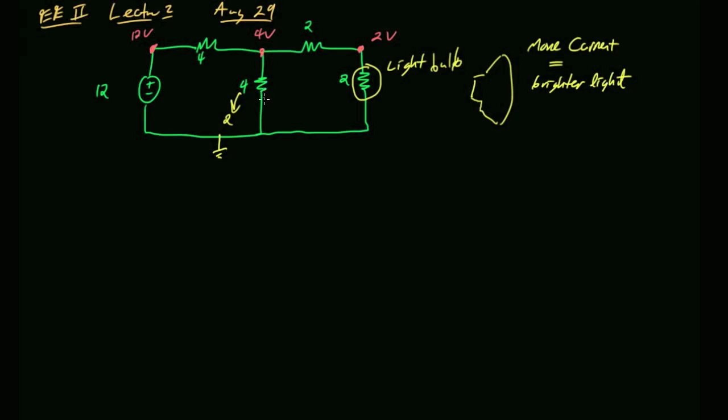Stay the same is an option. Can we argue that the light will get dimmer? Why would it get dimmer? There might be a case for that. There's less resistance, so more current passes through there. Current will flow through the less resistance. If this resistance gets lower, then electrons that make it to this intersection are more likely to want to go this way, because they prefer the path of least resistance. So it could be the case that by lowering this resistor, you divert more current into this path, which means less current in that path, which means the light gets dimmer.